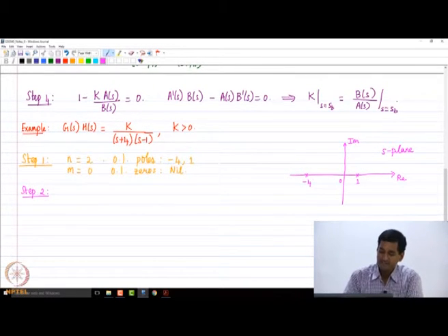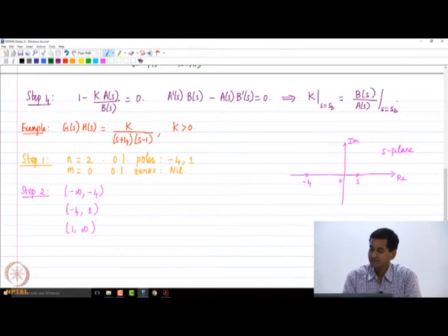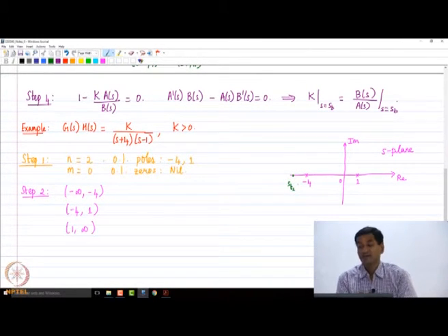So we immediately see that the real axis is divided once again into 3 regions, -infinity to -4, -4 to +1, and 1 to infinity. So now if we take a test point here, ST1, and then look to the right, how many open loop poles and open loop zeros do we have? 2, and that's even. So now -infinity to -4 lies on the root locus. So now what about -4 to +1?